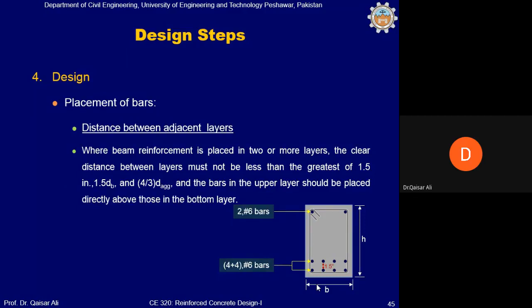स्टेज 2 का सिर्फ एक फायदा है कि स्टेज 2 में आपके क्रैक्स जो हैं ये बिल्कुल नहीं आते, और आते भी हैं तो उतने नैरो होते हैं even at ultimate load कि आपको पता नहीं चलता है। लेकिन अगर स्टेज 3 की बात करें तो स्टेज 3 में क्रैक आपके आएंगे, ऊपर बढ़ते जाएंगे, वाइड भी होंगे, और उसमें आप बीम की डिफ्लेक्शन भी देख सकते हैं।